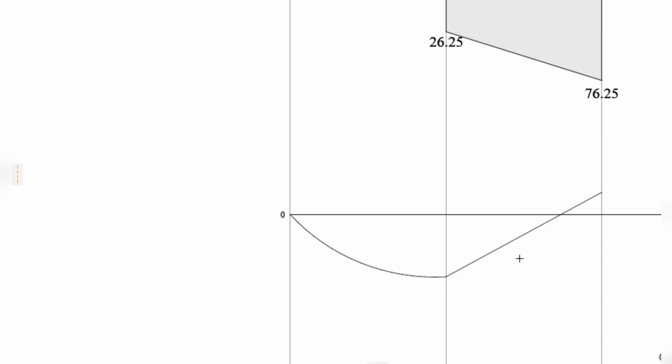We subtract this value, that is the 102.5 kilonewton meters, from 77.5 kilonewton meters, since our section is on the negative side of the shear force diagram, to get negative 25 kilonewton meters, that is on the negative side now of our bending moment diagram.